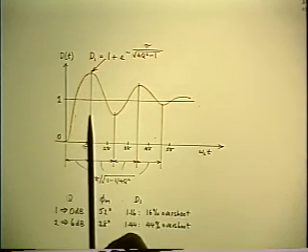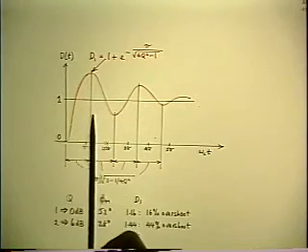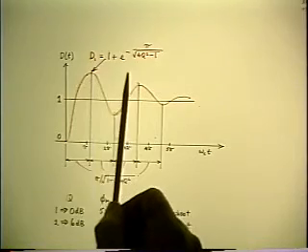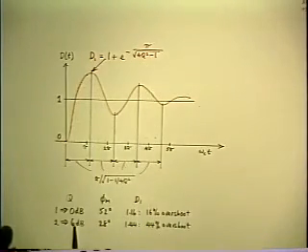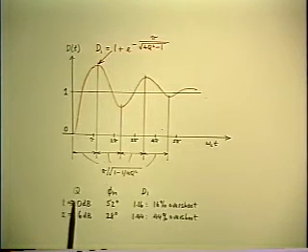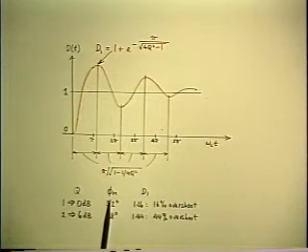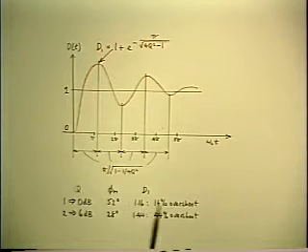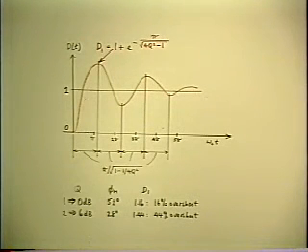And the important part of it usually is what is the initial overshoot, and you can find that pretty easily. I called it D1, the first peak, and it's a function of Q. And here's its value for a couple of interesting cases. The transition case where Q is equal to 1, corresponding to a phase margin of 52 degrees, the consequence of that is you get a 16% overshoot in the time domain, which isn't that much, and that's why it corresponds to the transition case where a little bit of peaking corresponding to Q of 1 isn't bad.